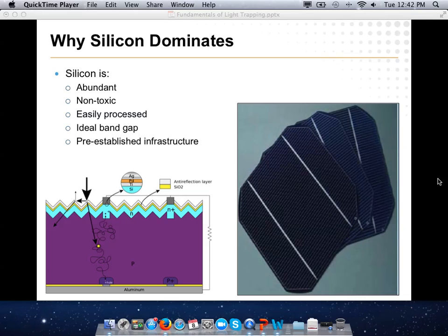You have a piece of silicon, and it's p-type doped here, n-type up there, and you can't really see it, but there's these little islands of p doping on the bottom here. And here's a ray coming in from the top, and that's where it's being absorbed, and you create an electron-hole pair. There's this little sort of Brownian motion where the electron wanders to the n-type, and the hole wanders down here to the bottom. And that is an excited particle that can be used to do work.